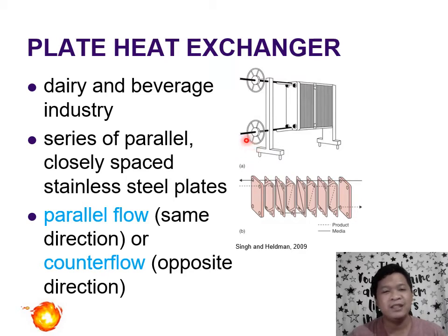Amazing, di ba? Alright, so it's called a plate heat exchanger because there are a series of stacked plates, as you can see here. What happens is that the heating or cooling medium and the food product flow on alternating plates. So kung the even number plates, nandyan yung mga heating medium. Sa odd numbered plates naman, andun yung food product. Okay, there are videos in the next few slides to be able to see